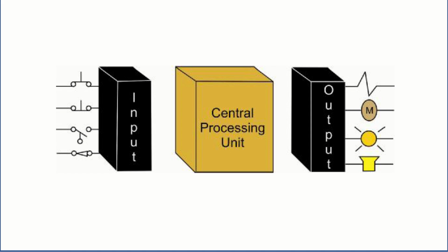However, you need to be very considerate about the signal level that is generated by the sensor at the output, because unless it is compatible to the standards of the PLC, that is, if the PLC is having a 4 to 20 milliampere input card and your sensor is giving out a signal of 0 to 10 volt in full scale, then they are not compatible. So accordingly you need to decide which sensor has to be applied.